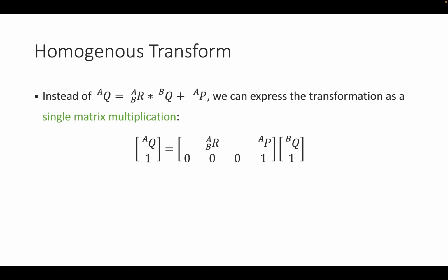Now, there is a better way to do these coordinate transformations that you have now played with a lot with the laser scanner, assuming you watched the detailed videos on Coursera. Instead of writing this complicated combination of rotating and then translating, we can also express this transformation as a single matrix multiplication. What I've done here is I created a 4x4 matrix, and I multiply a 4x1 vector. And what I get is a 4x1 vector that consists of the 3 points that I'm looking for and a dummy 1. Now this dummy number 1 here doesn't do anything. It really only helps us to be clear here.